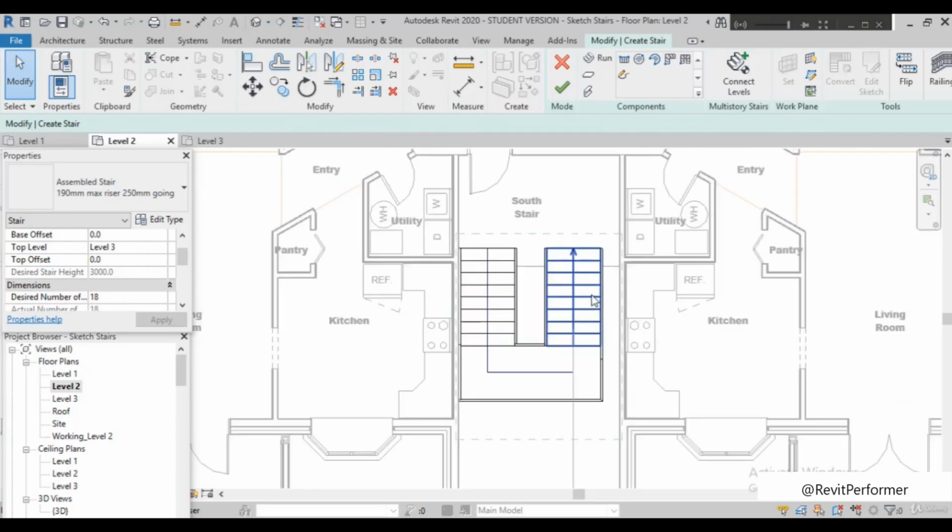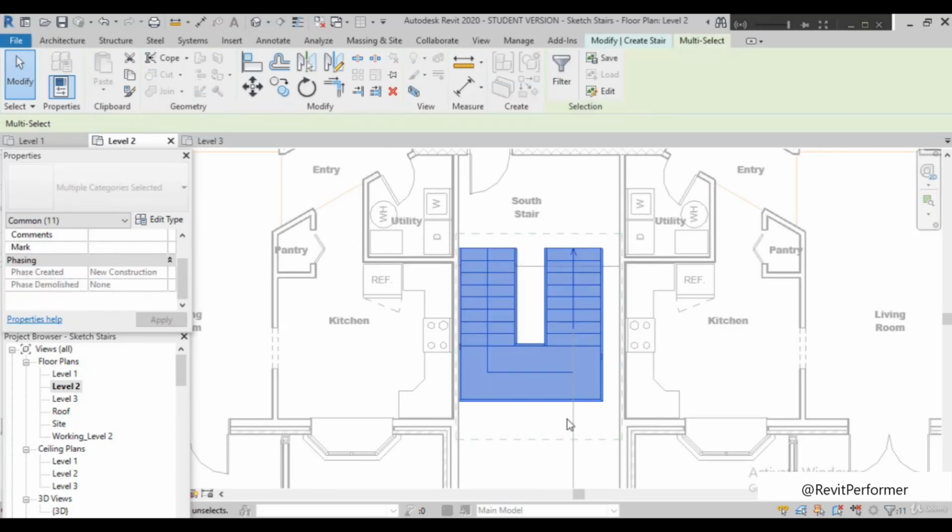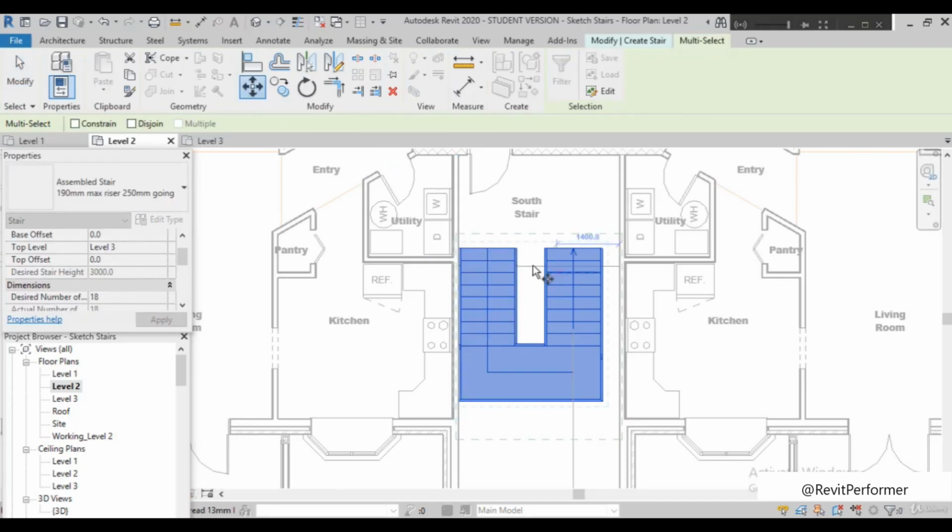One thing I just forgot. This is the straight movement that you find here. When you go to the move command, the first option, if the checkbox is on, it will not move at angles. It will only go horizontal or perpendicular. So be sure that this option is unchecked, so that you can move it anywhere you want. Sometimes users are in trouble with this because they don't find what to do. So this is very important.